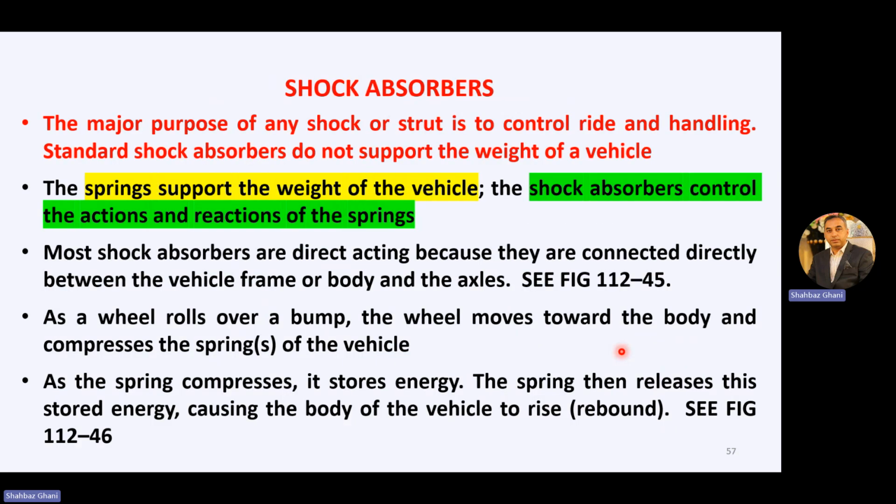Now the next part is the shock absorber of the suspension system. The major purpose of any shock or strut is to control ride and handling. Standard shock absorbers do not support the weight of the vehicle. The spring supports the weight of the vehicle.